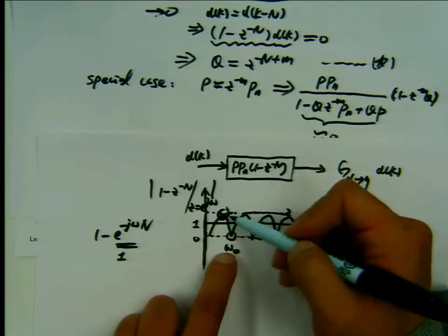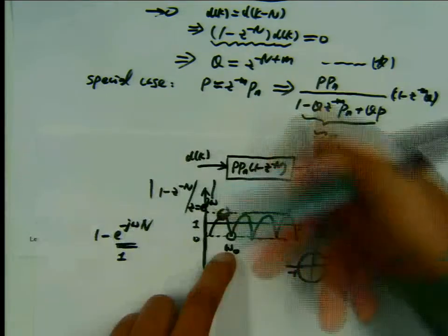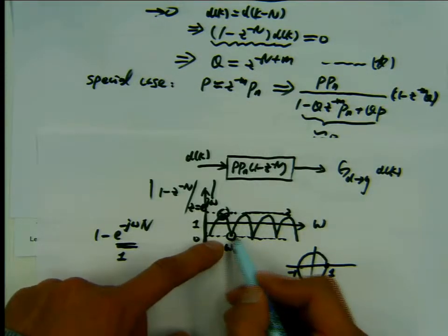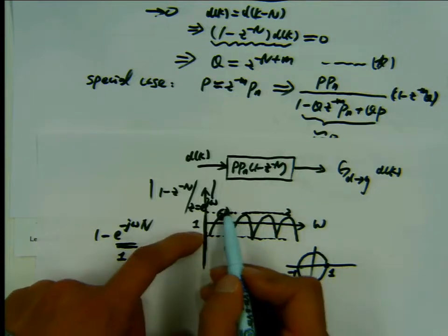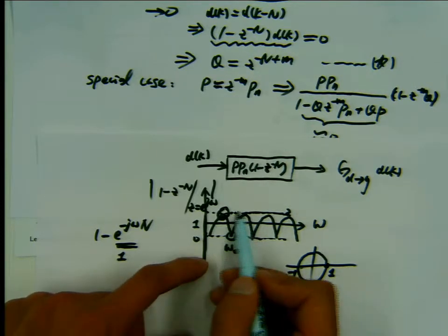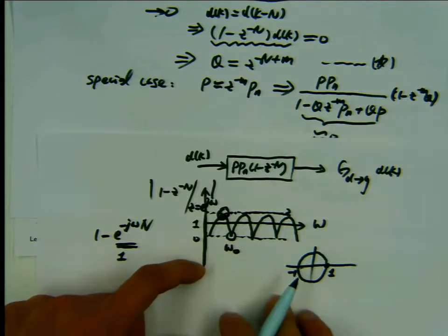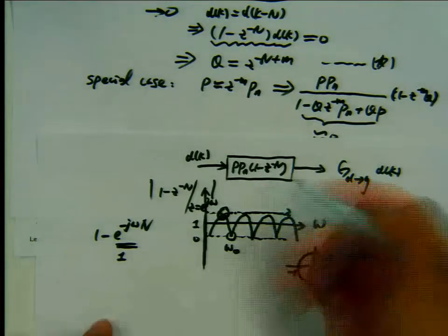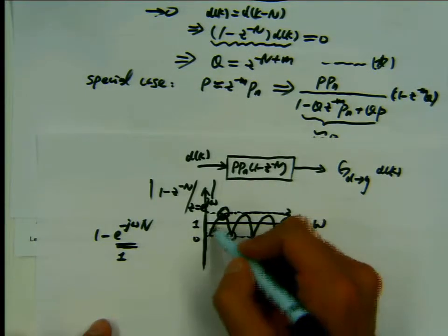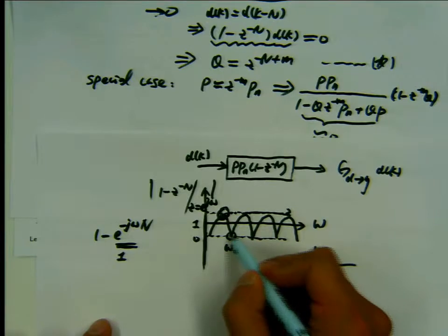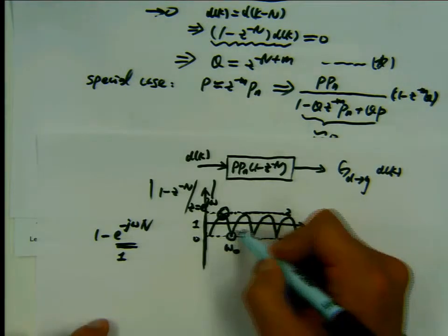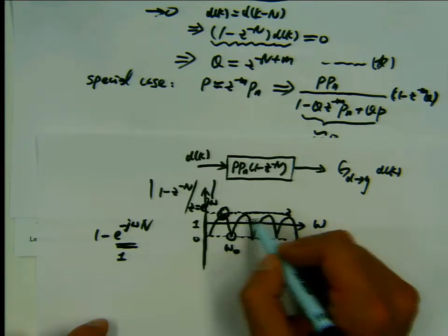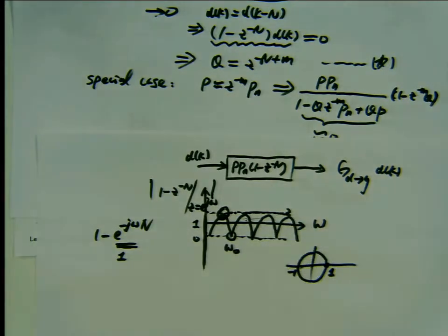It's amplified. See? Now you have exactly a practical design problem. You have achieved your disturbance rejection at certain frequencies, but unfortunately, you have amplified the signals at other frequencies. So if you are given this problem and asked to improve it, you might want to think about how you can keep this 0 magnitude for disturbance rejection, and in the meantime, how to reduce these amplifications here.